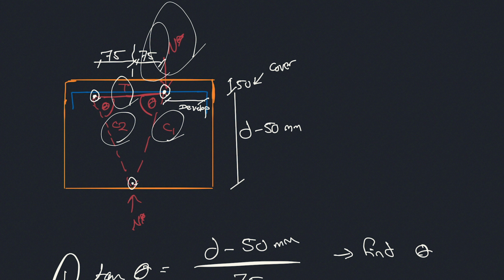Another thing that's important to consider here is the geometry, because the geometry is important in working out your forces, just like how the geometry of a truss is really important. So to work out this angle and resolve your forces internally for the tie member and for the compression member, you'd actually need to work out how much is the depth from the tie to the node at the bottom over here. Generally, if you have a 50 mil cover at the top, then that is where your tie reinforcement is going to be located. So you already know this distance, and at the bottom you can take about 50 mil to where the center of the node will be, just roughly, and that would be sufficient.